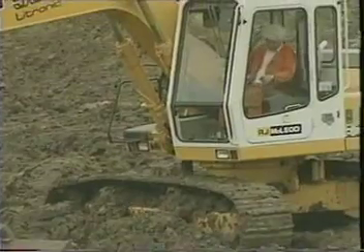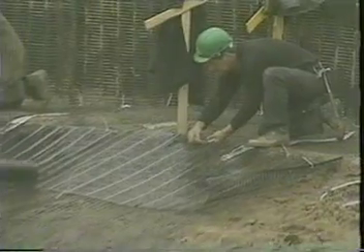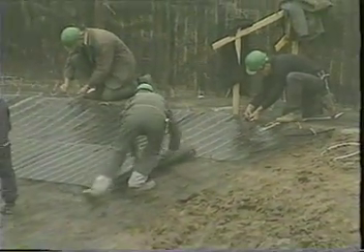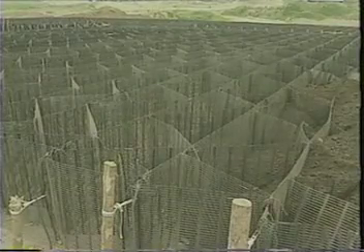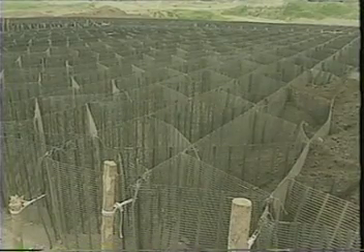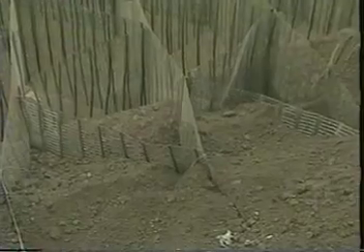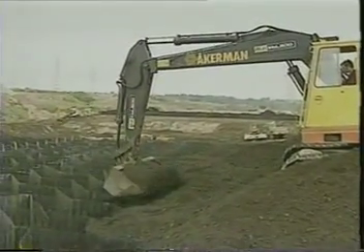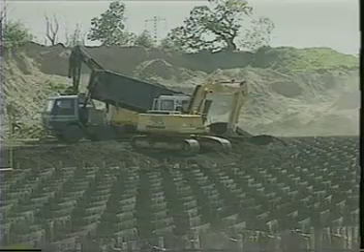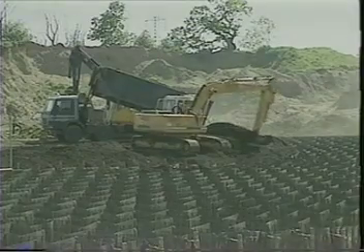Where the depth of the soft clay foundation soil is limited and there is a competent stratum below this, reinforcement may be obtained by installing a basal mattress. This consists of a series of interconnected geogrid cells constructed on the surface of the foundation soil. Filled with selected granular material, the cells form a foundation raft for the embankment.